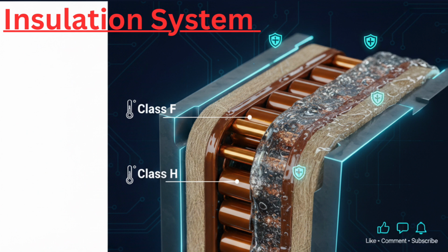Insulation classes such as Class F and Class H specify the maximum permissible operating temperature. In marine environments where humidity and salt contamination are present, good insulation protection and regular insulation resistance testing are absolutely essential to avoid earth faults and catastrophic winding failures.